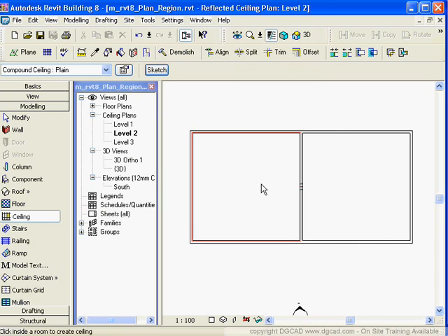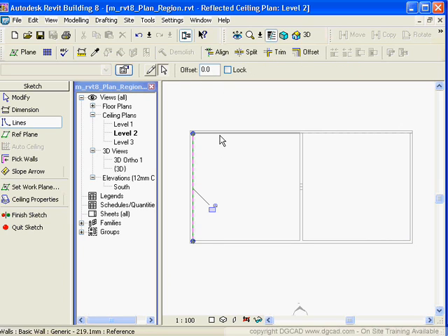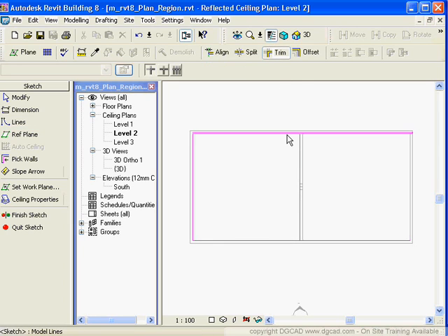So there's my ceiling grid that's going to come in, and as I place it, I click on the ceiling, and then I can go into sketch mode, and what I do is I say, okay, well, I'm just going to do, you know, basically it's just like doing a floor. I can use pick point, and I can pick the insides of these walls and then use my trim. So it's that same old sketch mode that we've seen in the past for doing a ceiling plan.